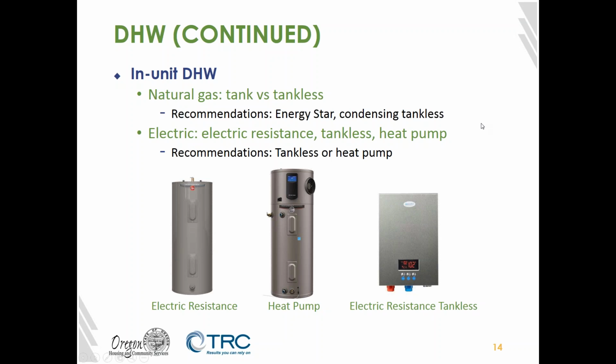The other option are tankless water heaters, and they exist for both electric and natural gas water heaters, and they use much less energy because they only run when there's draw on the water heater. And for in-unit systems, there isn't draw that often, and so that means they don't need to run very often. However, they tend to have much higher required loads, and so you need to have a building that will be able to fit that. So either on the panel for electric tankless water heaters, or the gas line needs to be large enough to handle that for natural gas water heaters.